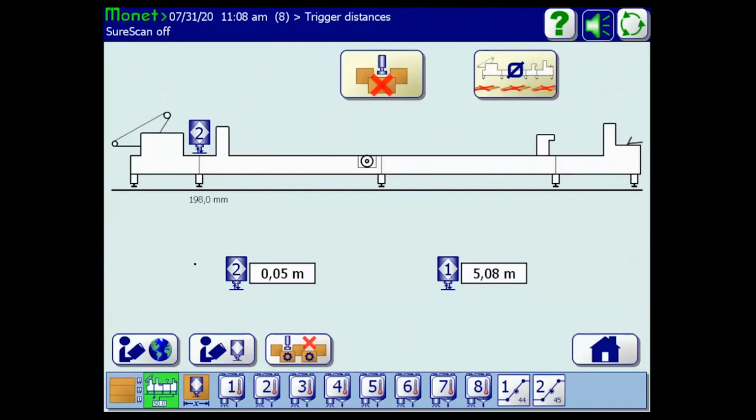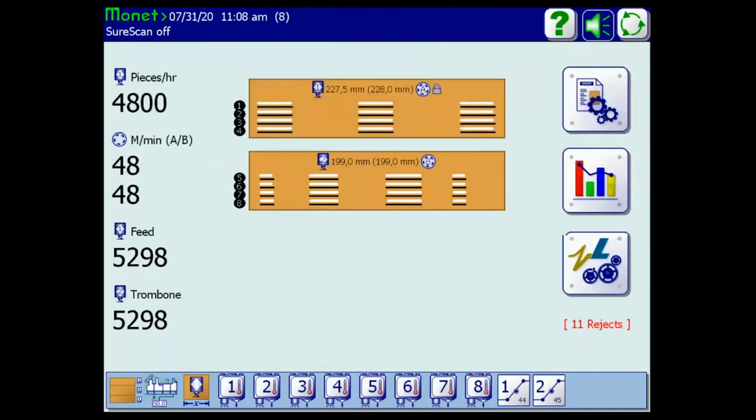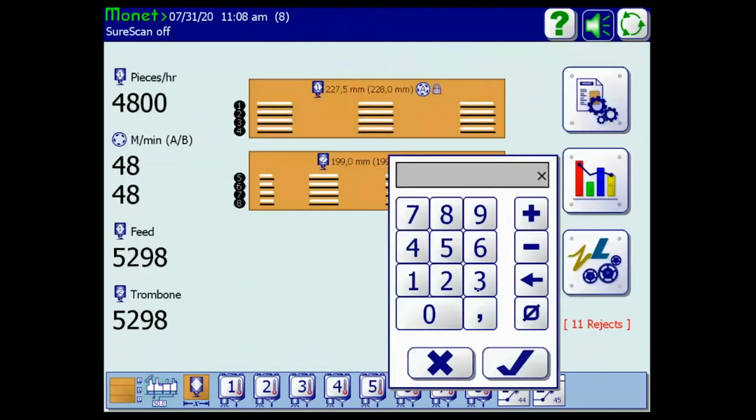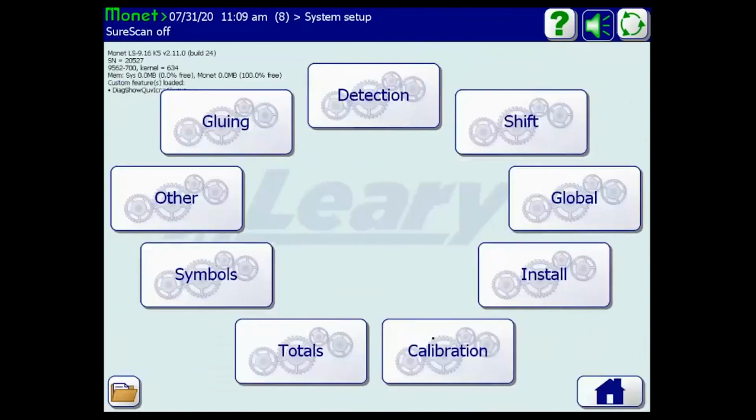What that allowed me to do is everything just before trigger 1 is encoder B, and everything before that point has trigger 1 assigned to it. So whatever this distance was when I did my master learn, trigger 1 to trigger 2, I just programmed something slightly smaller into the transfer distance, and that automatically put trigger 2 on encoder B and kept trigger 1 on encoder A. That's what you're seeing right here on the calibration menu.